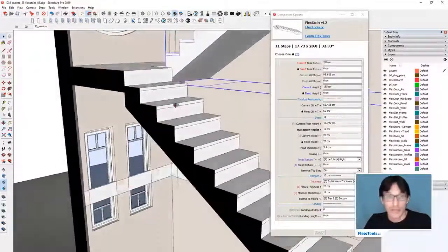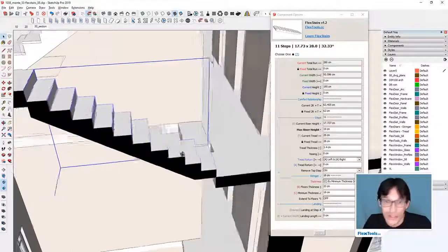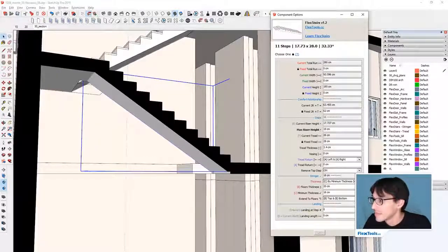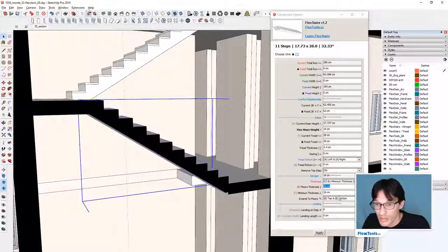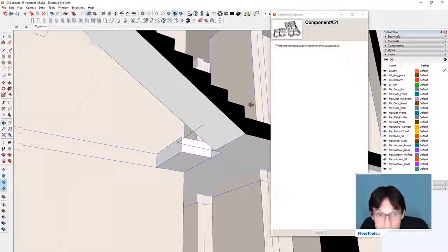Okay, we're going to do the same for the bottom stairs. We're going to extend it both to the bottom and the top all at once. Top and bottom. And I forgot to change the floor thickness. Notice right now it's for a floor that's 20, also here and also on the top. We'll change that to 25. And there we go. Okay, perfect.